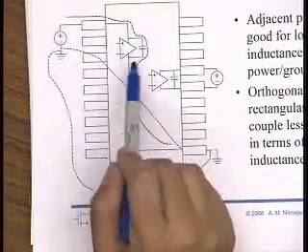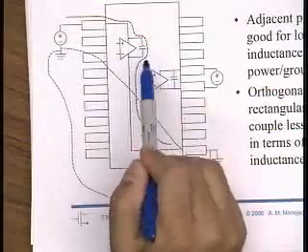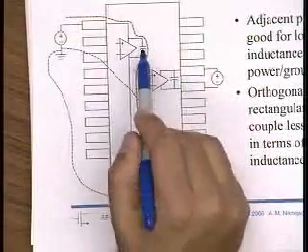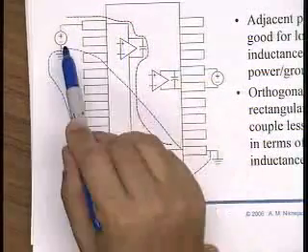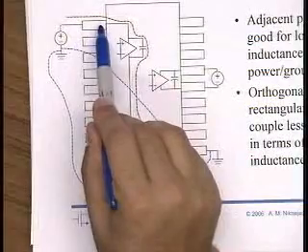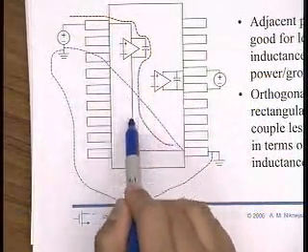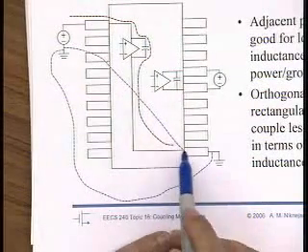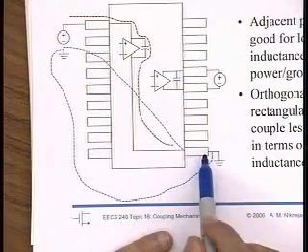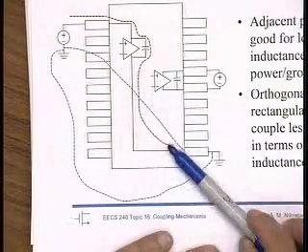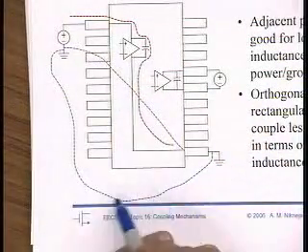But here's an amplifier, and I'm supplying VDD and ground to it. And of course I put in some local bypass capacitor. And then I want to know what the path is around the loop. So I go from here, through this pin, through the bond wires, come on chip, through this bypass capacitor, come down through these leads, all the way to this ground connection here. And then this ground can either flow through the ground plane, maybe it would take this path, or if there are onboard traces, it might take this path.